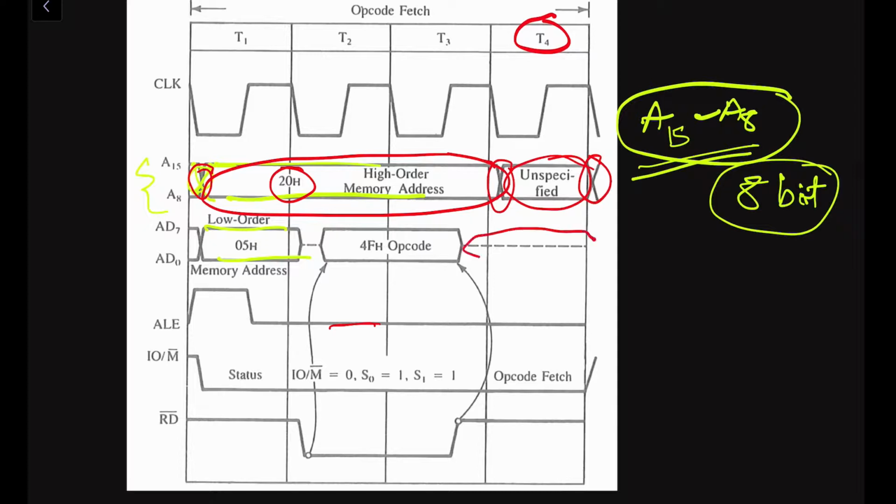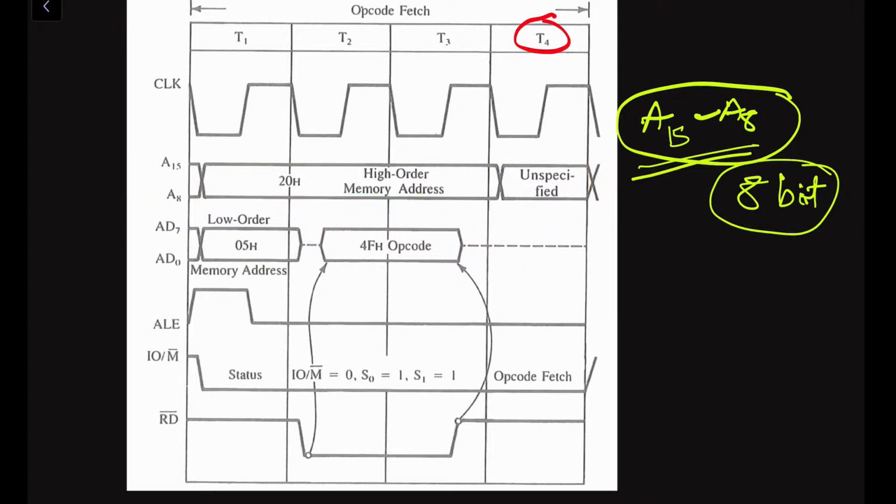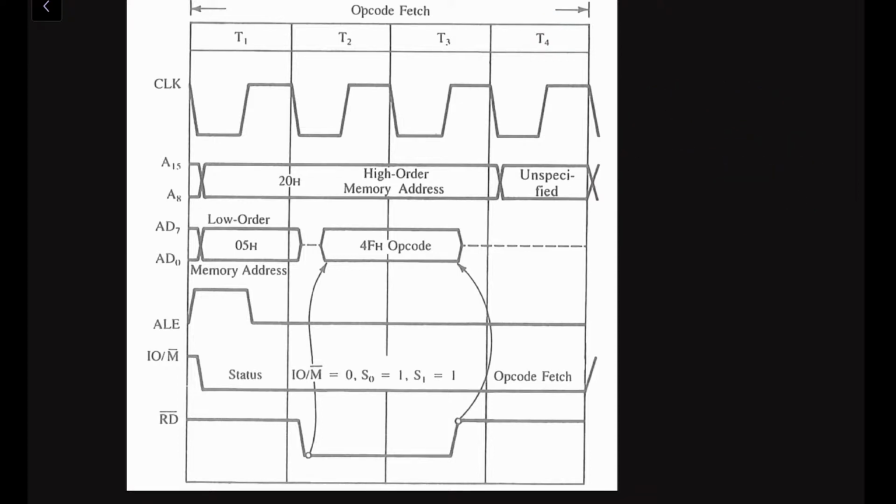Here we have already seen that these dashed lines are the high impedance states. There is ambiguity in the information, or we cannot directly predict the content during that cycle. So while drawing this timing diagram, you have to keep in mind when the signals are going high and when the signals are going low. Timing is the most important part in the case of a timing diagram.